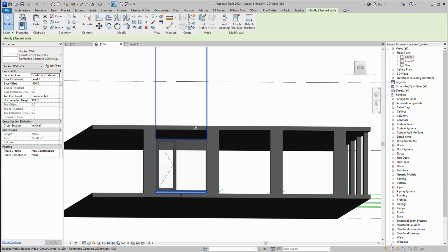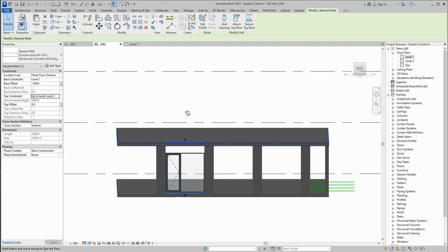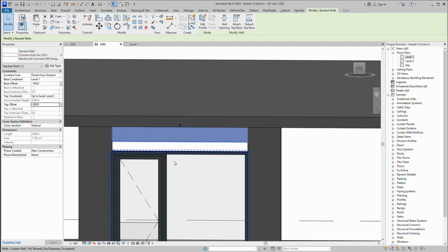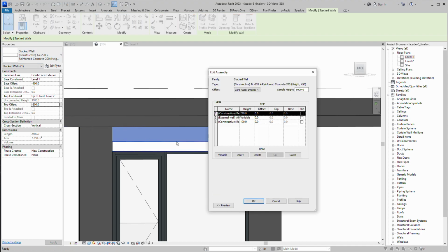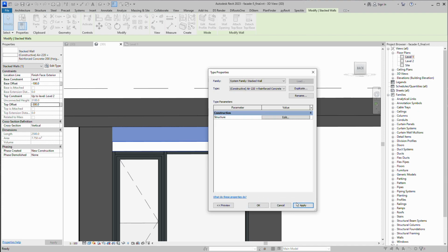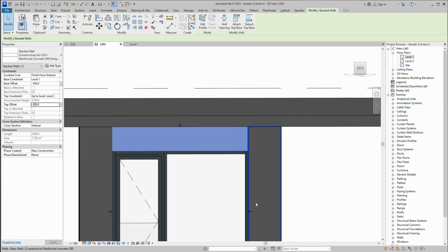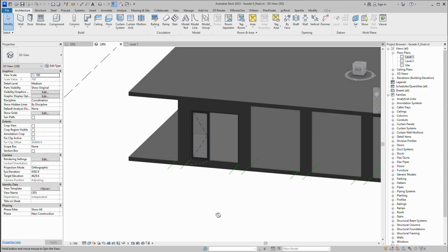And now we need to be careful. Oh my god, it's going only to level 2. After that, it's minus 300 millimeter. Now we need it to be about twice the distance. So 300 millimeter, 400 millimeter at least, I think. I will apply it. 400 millimeter and 50, I think. 450. Yeah, it's exactly 450. And as you can see, we exactly placed our future window.